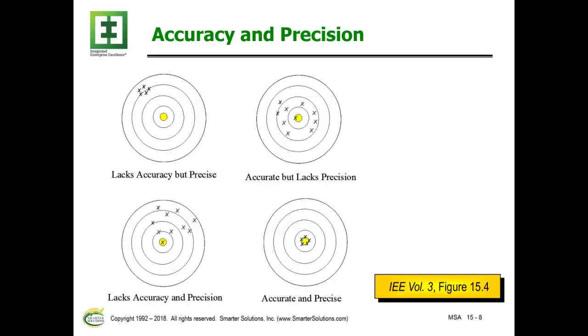So what we're really trying to do is address the accuracy issue. We're trying to get it so the average value is at the center. We could have a very accurate gauge because of our calibration, but it just does not have the precision. It's got a lot of spread to it. So the gauge R&R addresses the variability that we have within the overall measurement.